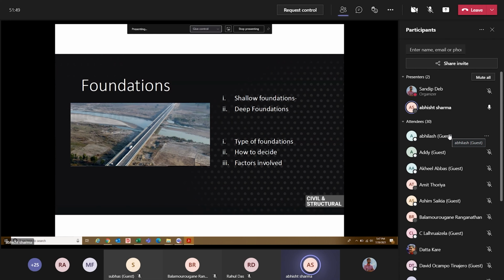Then how do we decide these? There are various factors, various site studies, various river studies: what kind of river we have, what kind of geotechnical recommendations we have, what kind of soil we have, and if there are any earthquake components that we have to check for, if we can go with the liquefaction or not. So there are numerous points that we need to figure out to finally come up with the thing which is safe in design and economic as well.